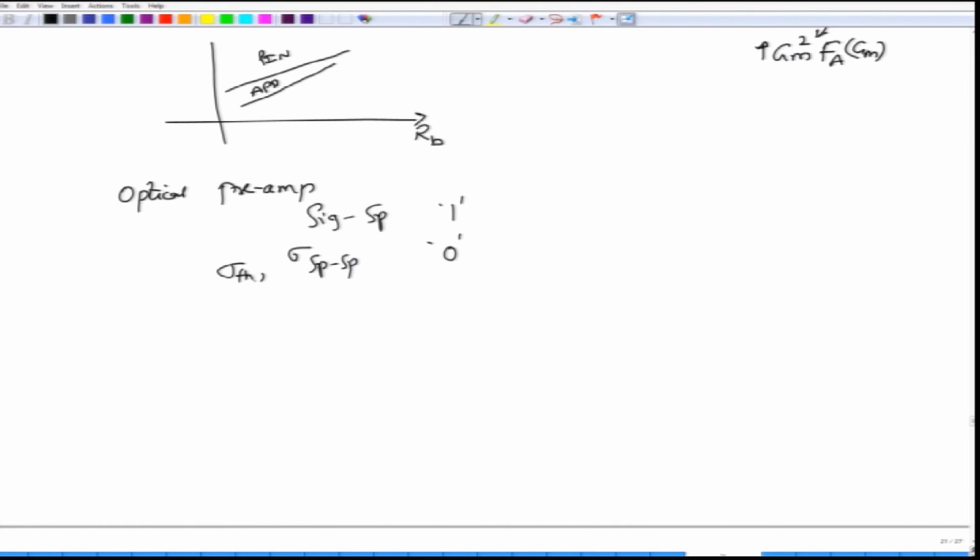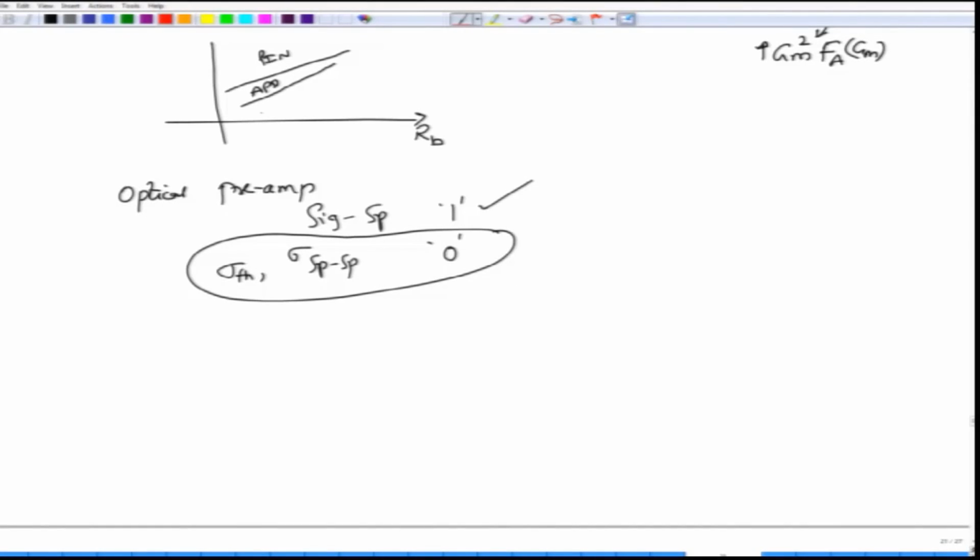What you get is only thermal noise and spontaneous emission noise, but these values are so small compared to the signal-spontaneous noise beating that one can neglect them in the expressions for the received power or the sensitivity of the receivers, with the result that the sensitivity actually gets better with the optical preamplifier. So, for the same bit error rate, the power requirement for the preamplifier goes even further down, and that is all happening because of the signal and spontaneous emission noise process.